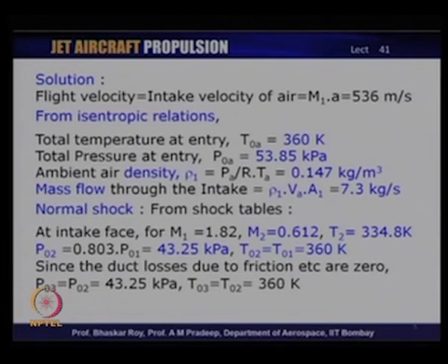So, that would be 43.25 kilopascals, and T02 correspondingly would remain same as T01. There is no change in total temperature across the shock, and that remains 360 K.